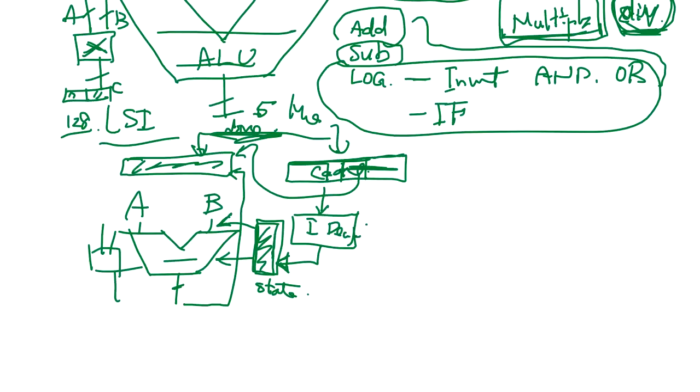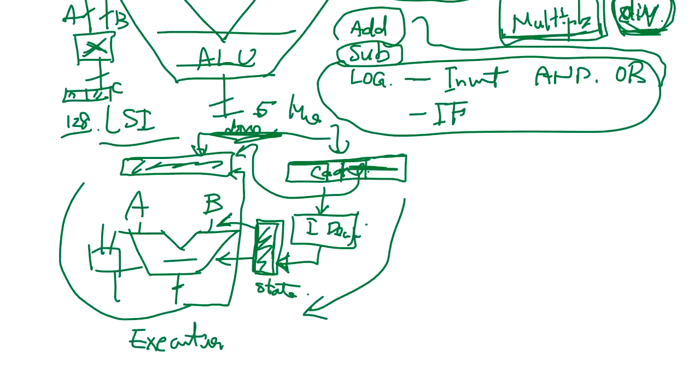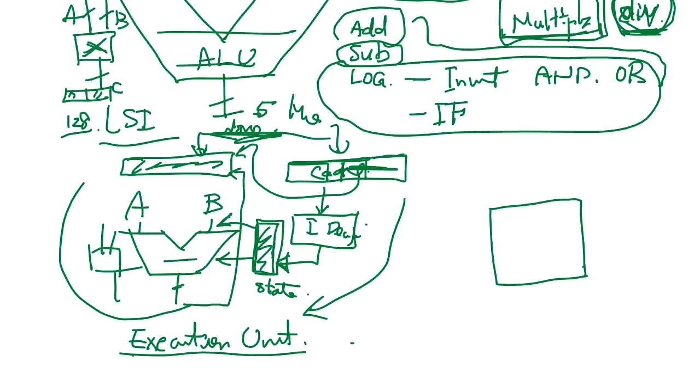So this side is the control side of the CPU, and this side is the execution unit of the CPU. That's the way a whole chip is created. If you look at the layout of the CPU chip, usually the register is big because each bit is a flip-flop, which costs a lot of gates.